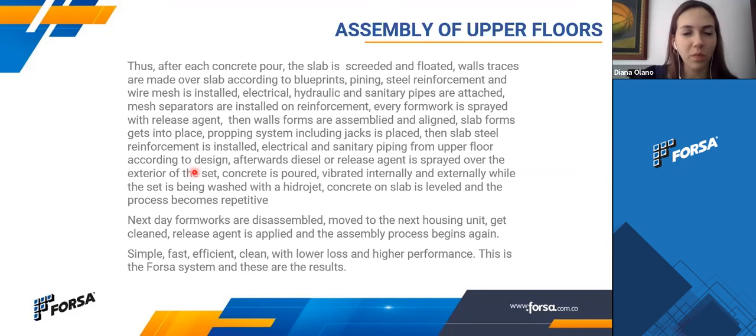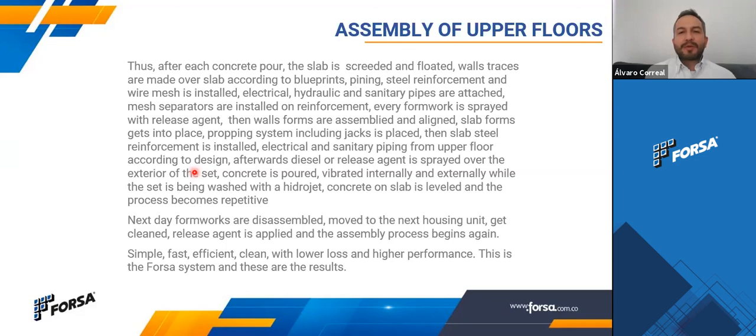Okay, yeah. You know that the aluminum forms are very lightweight, but when you have 27 kilograms every 60 cm, at the end, you don't have a very light structure. The whole set can be very heavy. So I haven't seen the concrete lifting or floating up the formworks. But anyway, what I have seen, and it's quite common, is that the concrete goes below, as you say.